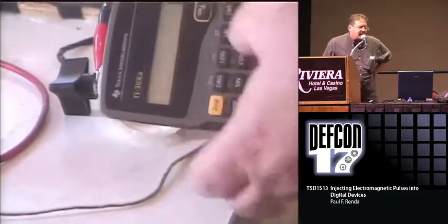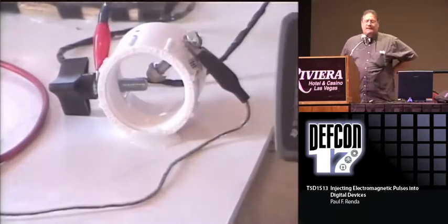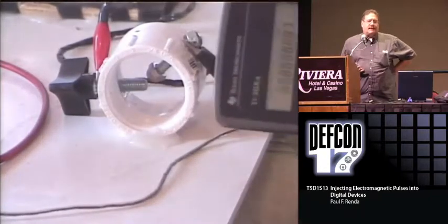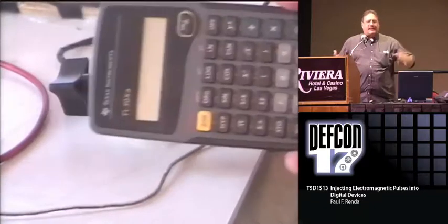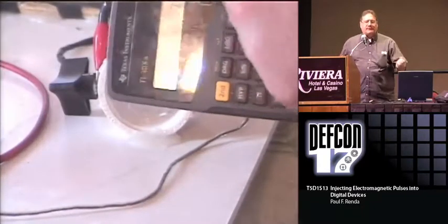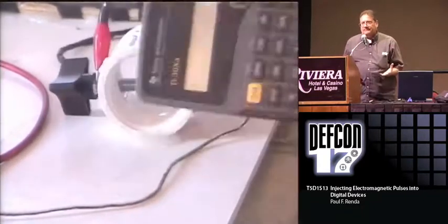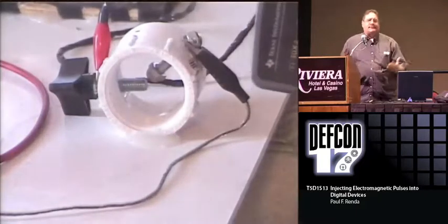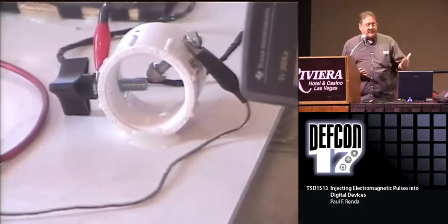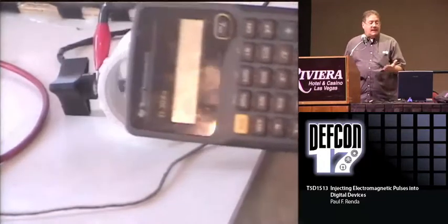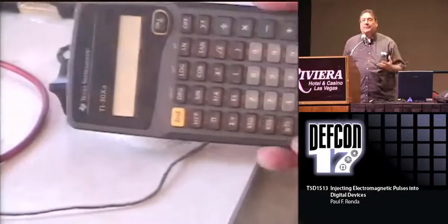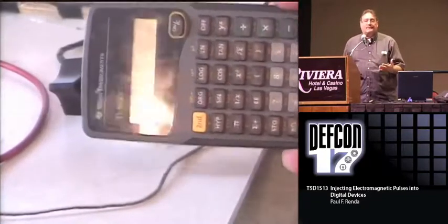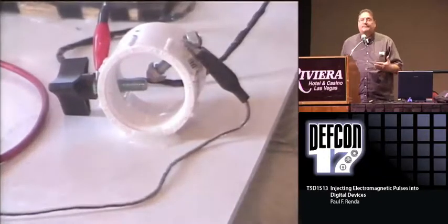The one other thing about smart devices is that they do have a memory. Qualitatively, I observed that when you pulse smart devices, you do cut down the life of them. In other words, if this device would normally work 5 years and you start pulsing it, it may only work 1 year. And I did find literature that validated what I was able to observe. So, it was a real event.